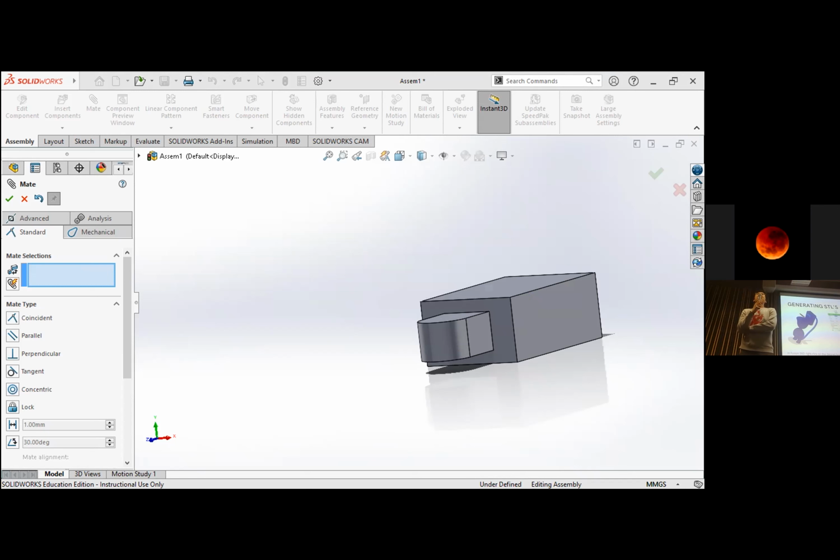So, different CAD programs have different ways of creating STLs. If you're using Fusion 360, you just go to each body on the left side, click on the body, right click on it, click Save as Mesh, and then in the Mesh option, select STL binary, refinement height, and make sure you don't check Center 3D Print Utility. Press OK, and then you have an STL. In SolidWorks, you just do a Save As, and that should be good.